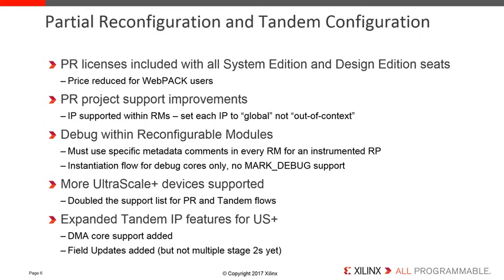Partial reconfiguration licenses are now included in all System Edition and Design Edition seats. Also, the price has been reduced for WebPACK Edition users. In 2017.1, partial reconfiguration includes the ability to set IP within reconfigurable modules and the ability to debug reconfigurable modules. For this, you need to instantiate a debug bridge in every reconfigurable module.